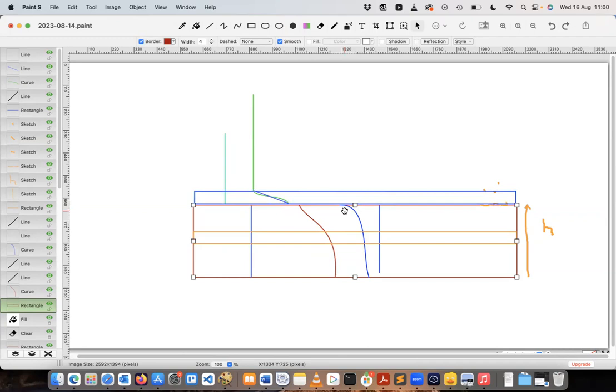So at the interface itself, imagine the skin of that interface. That skin has zero volume. It's not even the right word to use, because skin does have a volume. If you think of taking off your skin, it's going to have a certain thickness. We don't have to be so gory, but the interface here has no thickness. So if there's no thickness, there's no space to accumulate anything. And so the flux just above the surface must equal the flux just below the surface.